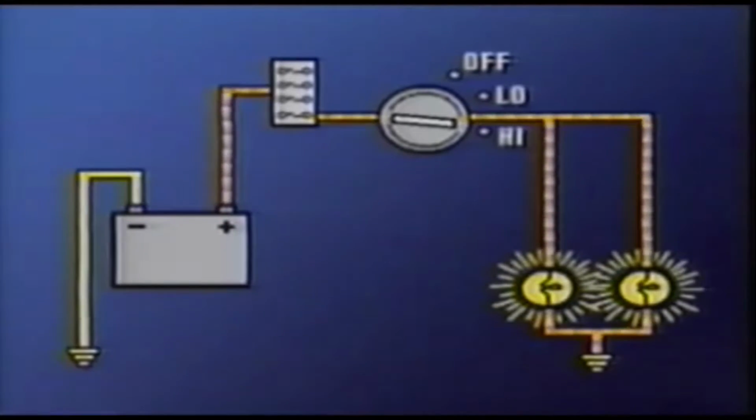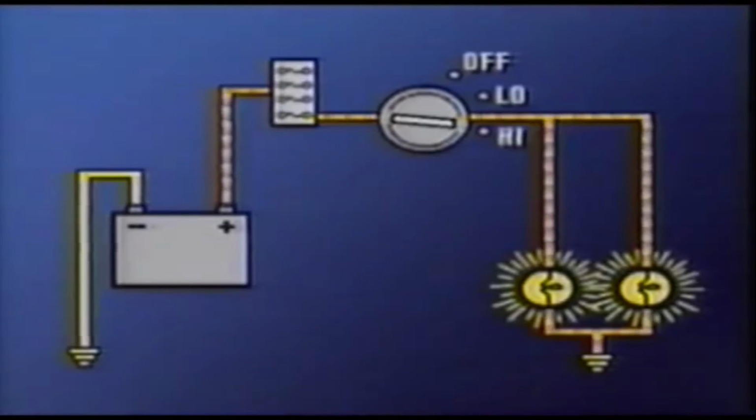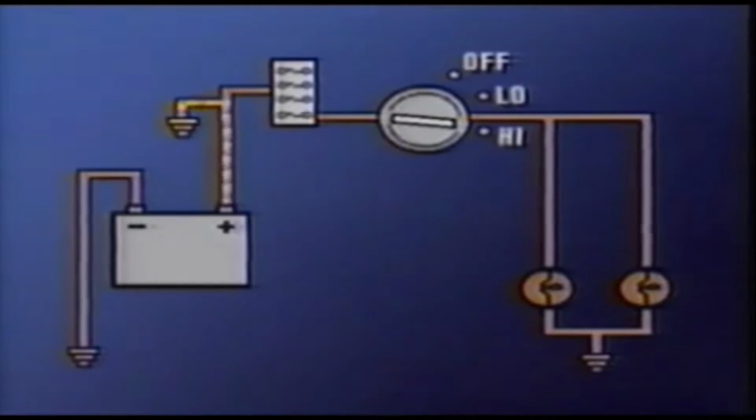Short circuits happen when an unexpected path to ground occurs. Examples include wires or components damaged in a collision, flood damage, or pinched and cut wires that can result from improper repairs. The location of a short in a circuit will affect the symptoms you find. For example, a short between the power source and the fuse will cause very high current flow and likely damage the circuit and the source.